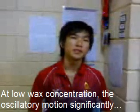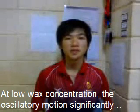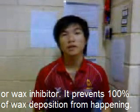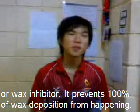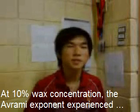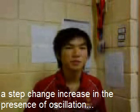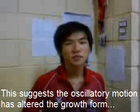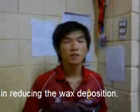At low wax concentration, the oscillatory motion significantly reduces the percentage of wax deposition without any solvent, enzyme, or wax inhibitor. It prevents 100% of wax deposition from happening. At 10% wax concentration, the Avrami exponents experience a step change increase in the presence of oscillation in comparison to those without. This suggests the oscillatory motion has altered the growth form, reducing the wax deposition.